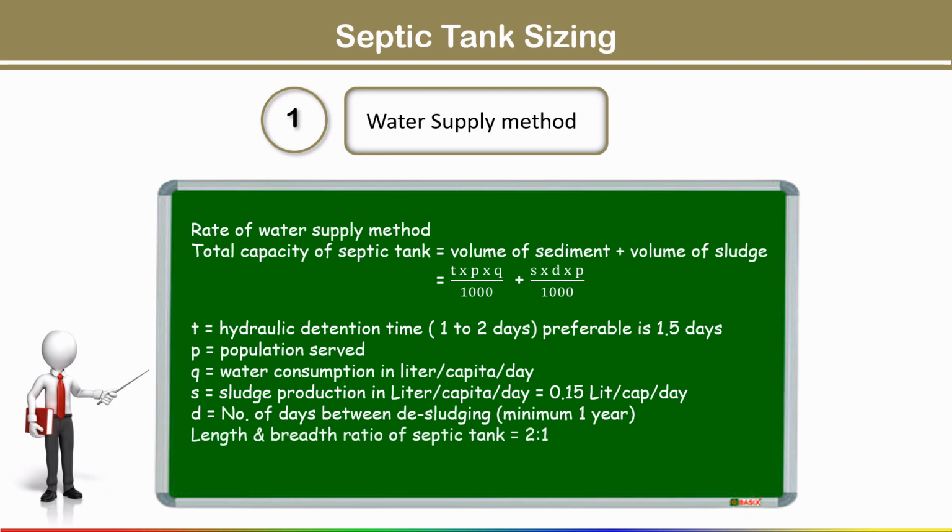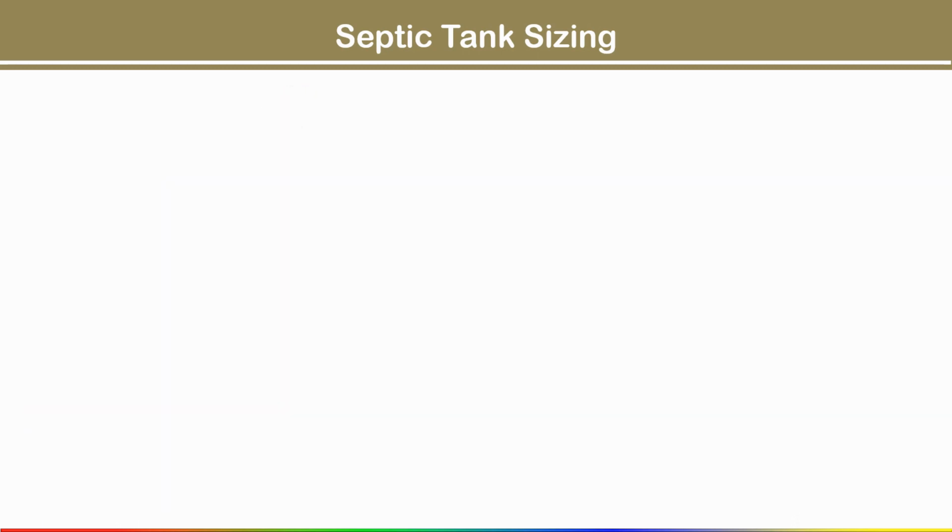And remember, while sizing the septic tank, we have to remember one point: the length and breadth ratio of the septic tank we always have to take as 2:1. Correct?